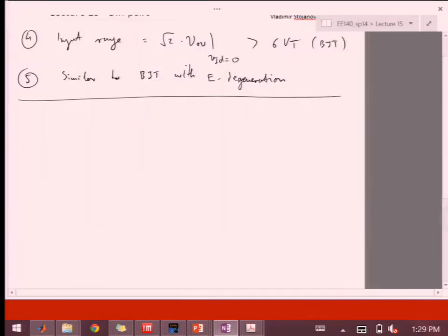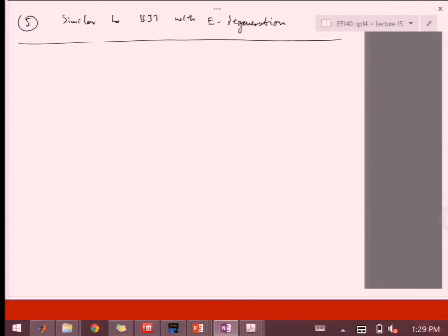As you can guess, the transconductance of the diff pair is somewhat related to GM in some way, right? And we'll see actually that it's a pretty simple relationship that we're going to derive. So let's take a look at how to do that. So far, we've sort of only seen how the current gets switched, but obviously you want the voltage at the output. So now you have to decide what you want to load this diff pair with, right?